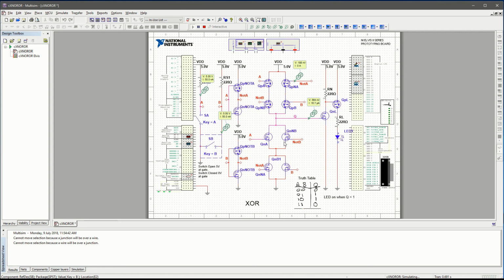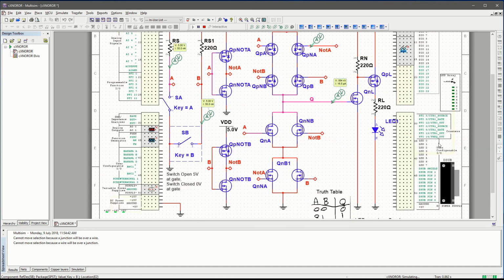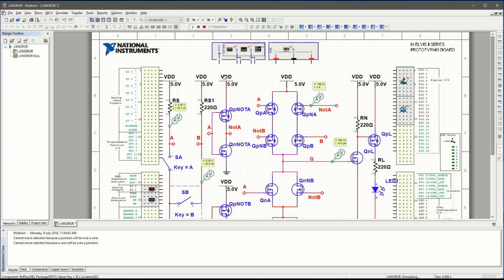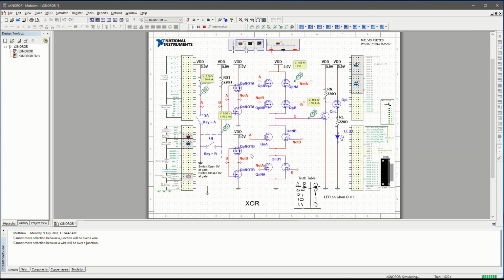You may have noticed before I put my two nMOSs here around the wrong way, and I had my source up here and the drain down here, and this caused a few problems. And also I gave it a separate VDD for the second switch as well. But that's all been resolved. So now we'll go and implement it on our actual breadboard.